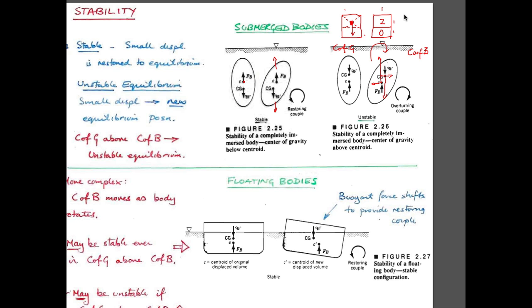So this is going to be the center of gravity in this particular case. If you look at the center of buoyancy in this case, then it doesn't care about the relative densities or the masses of these two components inside this. It sees a displaced volume in the upper part and in the lower part, and so the center of buoyancy is just going to be the centroid of this displaced water volume. And so that basically is this case where you have intrinsically unstable. If you happen to give it a small displacement, so these aren't quite in alignment, in this case they're absolutely in alignment, it's absolutely stable.